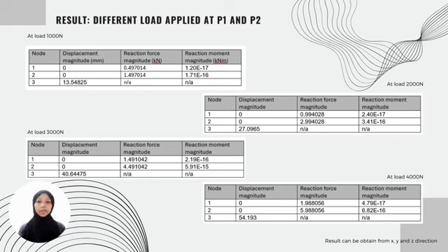So I will explain when the load is at 1000 Newton or 1 kilonewton. The data for node 1 and node 2 retrieve none or 0 displacement, while node 3 got about 30.548 mm displacement in y direction. That means node 3 implies a significant deflection after the load is applied.